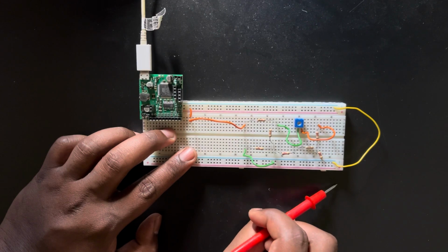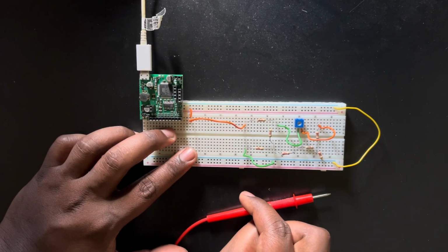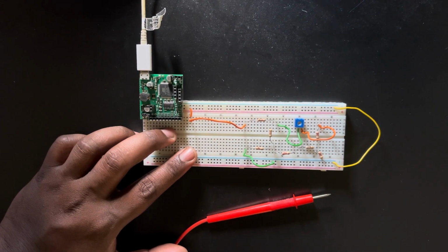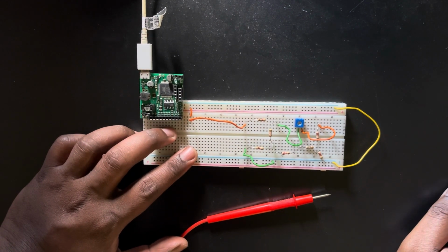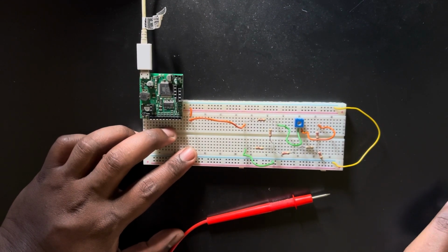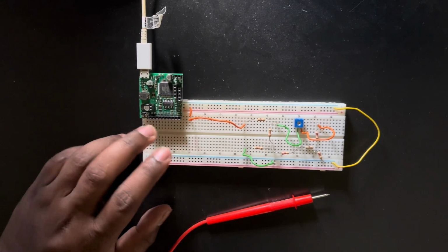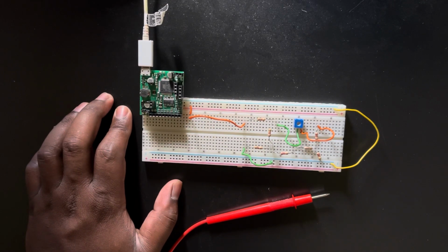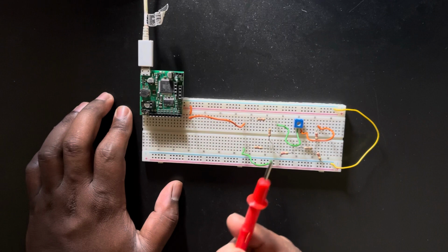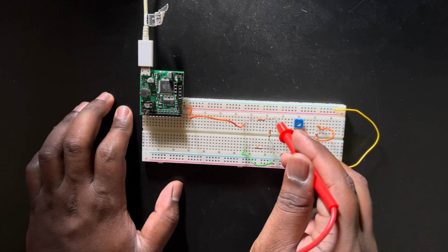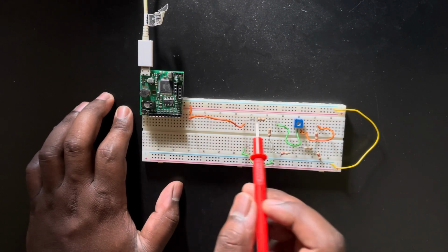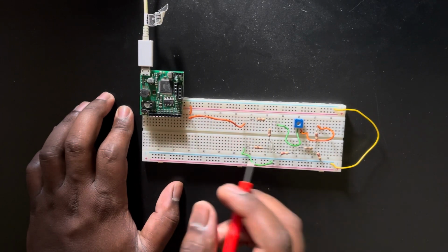If you see table 1, there are all the voltage measurements. You have to put all the voltage measurements there across every resistor, right? For example, when it says measure the voltage across node 3 and node 1, if you observe table 1, what you have to do is, when it says V31, that means the positive probe of the multimeter you put on node 3, and the negative probe you put over here, and then you measure the voltage.